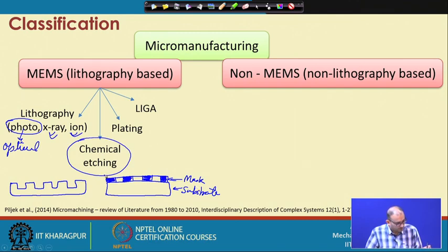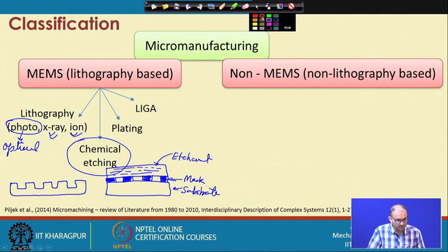and then you put a chemical on the top of this, etchant. So, what will etchant do? Etchant will attack from this particular location, because now etchant can enter and come into contact with this. But here it cannot attack, because this particular material is inert with this, because it has no chemical effect with respect to this.